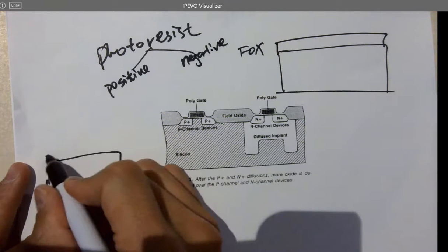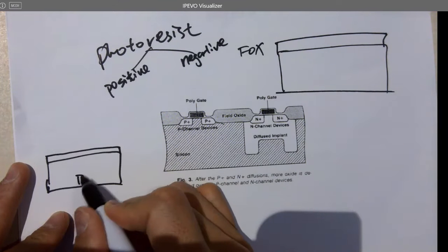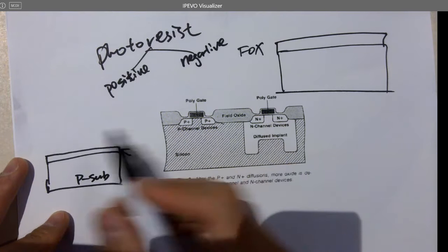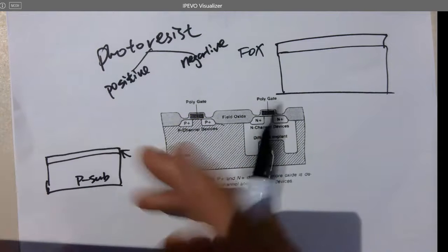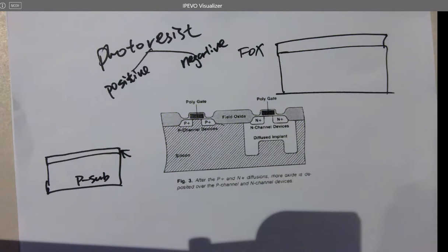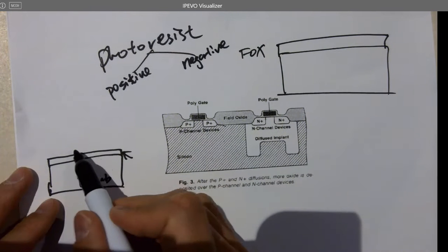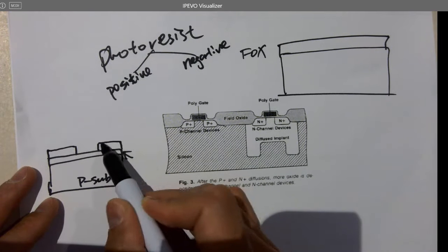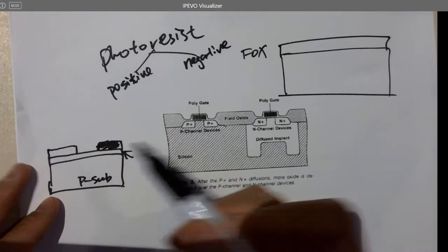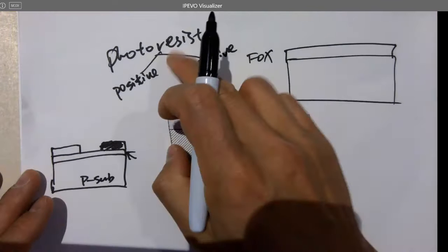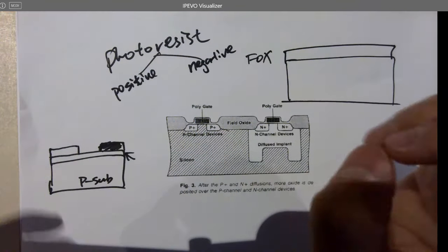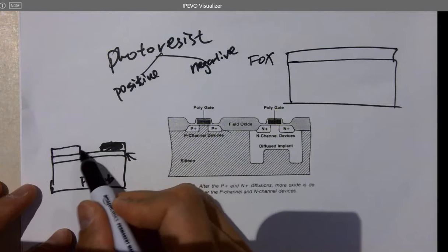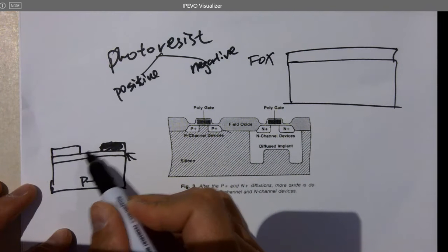So spin coat, photoresist, that's a wafer, right? That's a photoresist. And you have a mask, which you draw all the features like wires, whatever you draw in a layout, okay? And for example, here's the mask. These are dark, just ink, right? The ink is not a regular ink. It's a different material, has all the metal particles, which can totally block the UV. But this is clear. This is a clear plastic or the glass plate.